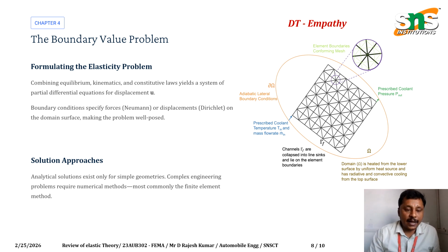So next is the boundary value problem formulation. When we combine three principles, that is equilibrium, kinematics and constitutive laws, that is Hooke's law, we get a system of partial differential equations for displacement. But here's the critical part: boundary conditions. We must specify either Neumann boundary conditions or Dirichlet boundary conditions.